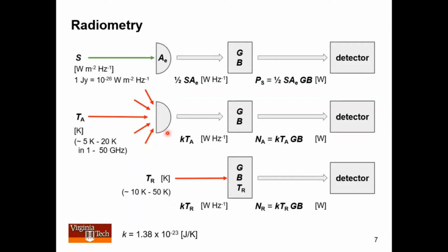Of course, the other thing we have to be aware of, especially for the weakness of the signals that we're interested in here, is everything else that the telescope picks up, which is not your signal of interest. As Joel explained, we also describe this in terms of a temperature, which causes a lot of confusion because it's Kelvin. But what it really is, is simply a way of describing the power spectral density at the output of the dish, watts per hertz. All you do is take watts per hertz, divide by Boltzmann's constant, and you get the temperature we're referring to. So this is the noise incident from all directions expressed as the power spectral density at the output of the dish, or whatever aperture you're using.